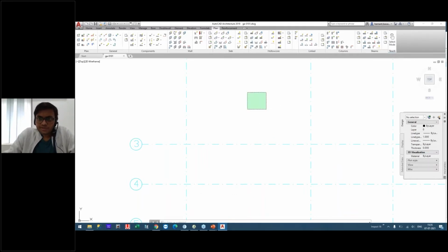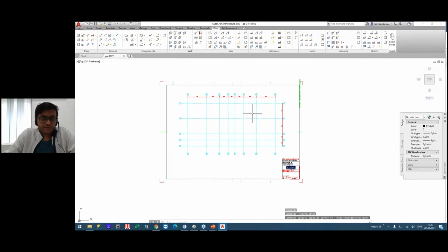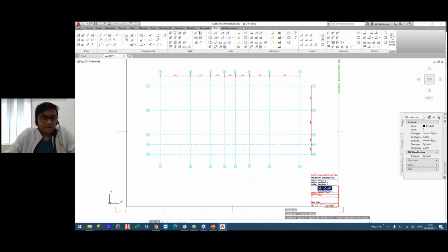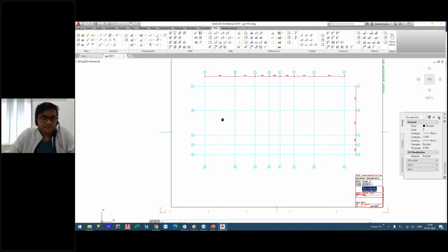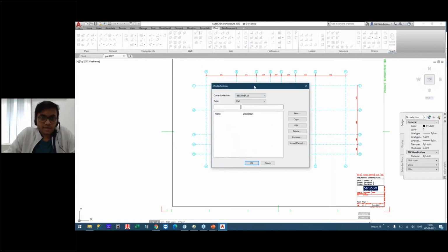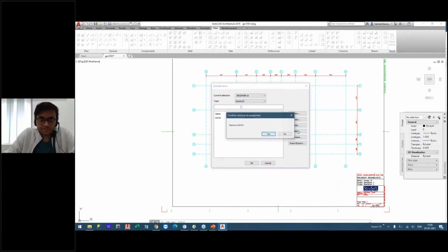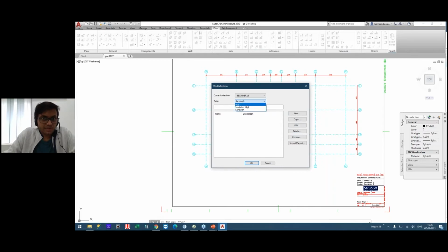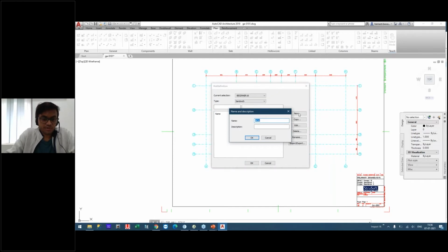Okay, so we are in our main view for the AutoCAD, and this is a floor plan. And for drawing walls, we'll first start by defining how we want those walls to be. So we'll go into the wall definitions. Currently I do not have anything on our project level. I actually have one, but I will just delete it. We'll start with the sandwich walls. I will create a new definition. Because I am using 340 mm thickness, I will be using that.